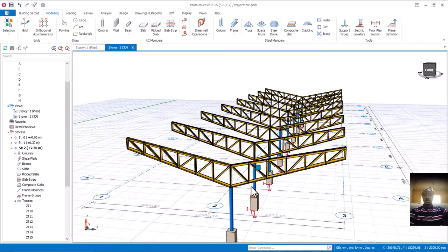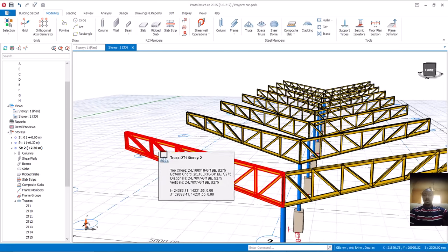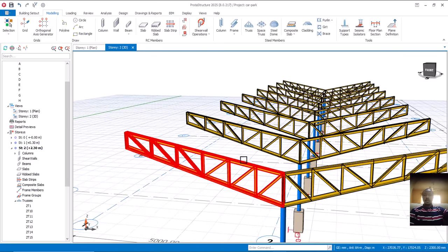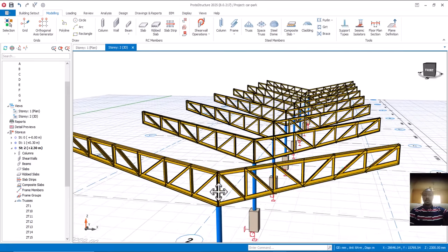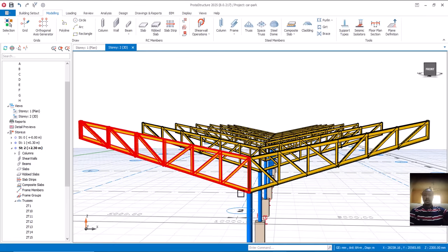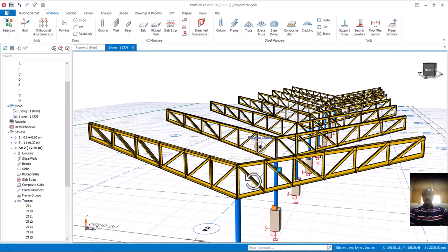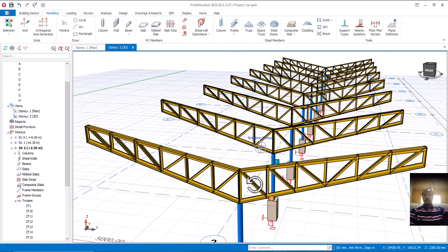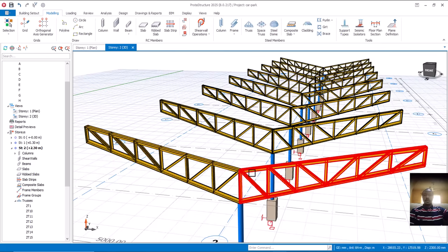So the next thing, if you look at this, definitely at site, they are going to form something of this nature. And once it's formed, they are welded together. The thickness of the welding here matters a lot. There's a calculation for that. That is why I said that in most of our videos we have been doing how to model, how to do connection, and how to generate your steel drawing.